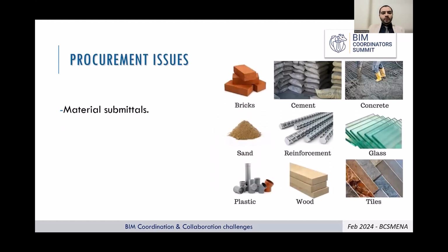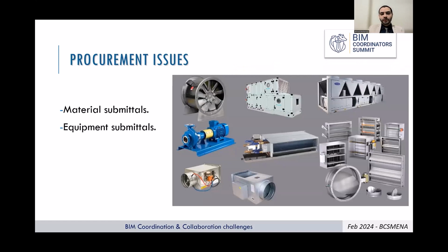We also have procurement issues. Material submittals should be submitted, approved by the consultant, and then implemented in the BIM models. In most projects, material submittals take time. So we have to work with proposed materials and then apply the submittals into the models. Also, attaching the submittals to the elements is very important, because it will be useful in field management and in the handover process of the project.